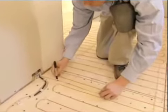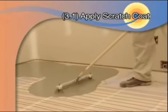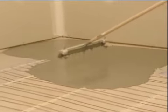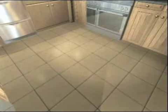Select a pair of 3-inch runs of cable on the floor to position the sensor wire. Create a channel for the sensor wire by cutting and removing the unused strapping. Fasten the sensor wire to the floor with the supplied clips, making sure you center the sensor bulb between cable runs. Using a thinset mortar installed with the flat side of a trowel or by spreading a self-leveling compound, cover the cable with a scratch coat layer. Once the scratch coat layer has cured, install your tile or stone using standard tiling procedures for concrete subfloors according to the Tile Council of America for the United States or by the Terrazzo Tile and Marble Association of Canada.